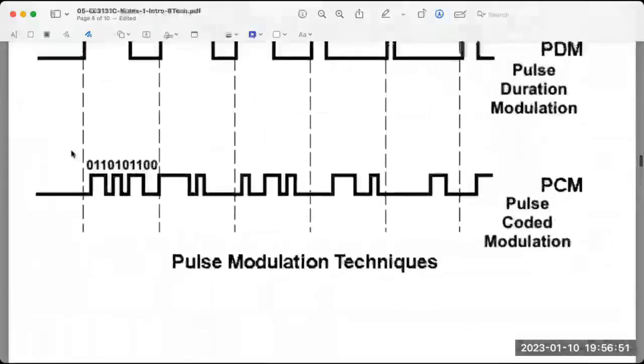The way to see it is to go back here and focus your attention here. If I transmit this waveform, at the receiver I want to recover that bit pattern. Once I get the bit pattern, I can figure out which level it was and find out the value. If it was a music signal, I can reconstruct it. So what decision do I have to make here? Your goal is to recover that. So how did we generate it? We use on-off keying. If there's a 0, no pulse. If there's a 1, there's a pulse. So at the receiver, you get this noisy signal. What are you going to have to do? All you have to do is decide, in this part, is there a pulse or no pulse? In this one, is there a pulse or no pulse? In this interval right here, is there a pulse or no pulse?